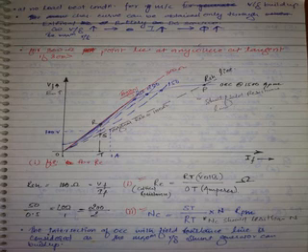Make a point R somewhere here, drop a perpendicular, and it will cut the original field resistance line at a point S. So RT in volts by OT in amperes is RC. RT represents OCC at N. The length of ST represents NC. If you plot OCC at NC, this is OCC at NC. So simply you can calculate ST by RT times that speed. Always ST is less than RT, so you will get NC less than N.